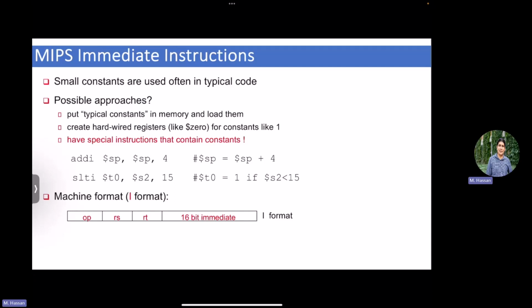So here, immediate operations, arithmetic operations, are very common, right? And we have already seen an example of this related to the memory operation. Remember, in the memory load or store, the format was that you have a destination register for the load, for example, but to compute your address, we needed an address that is stored in a register, and then there is an offset, right? For example, we said 4 and then R4. Then we said you add the constant to the register value to obtain the address. We needed an add operation. In fact, it's an immediate add operation, right? So it's very common in address resolving.